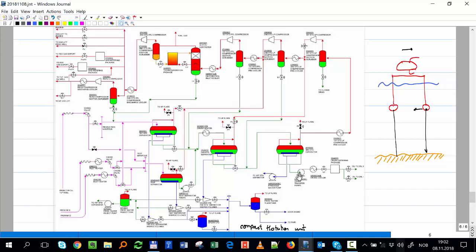The oil goes to the crude transfer pump, a cooler, and then the metering, and that's it. And then to export. Here I had no need for, and it's usually like that in the North Sea, we have no need for dehydration or desalting. 2% is enough. Some other places in the world have to have the coalescer. We don't have it here.